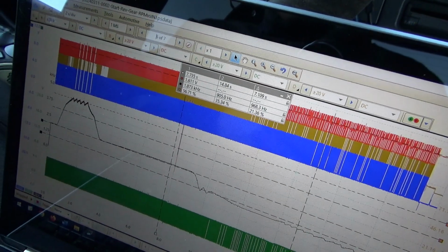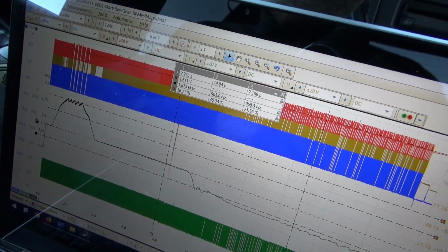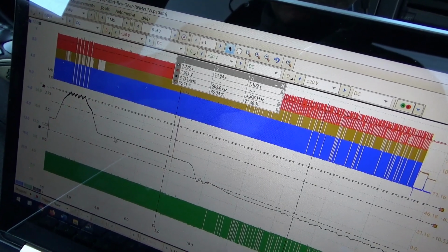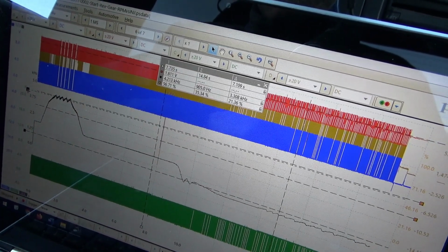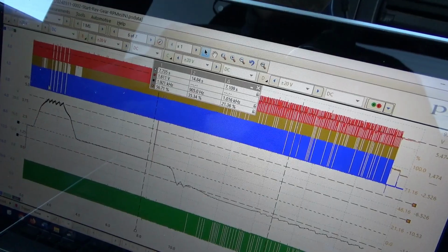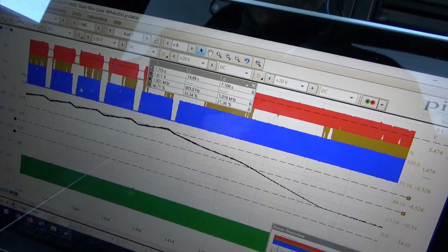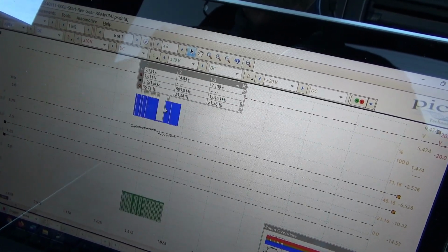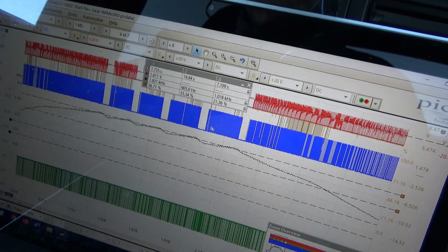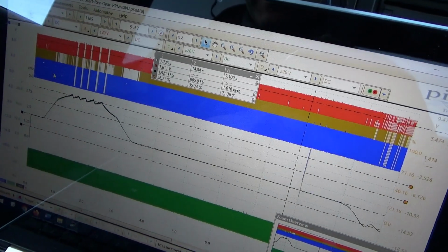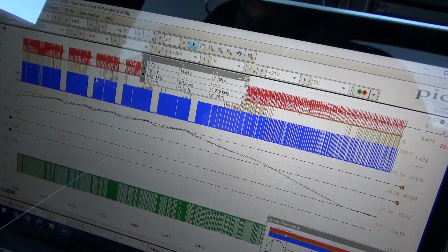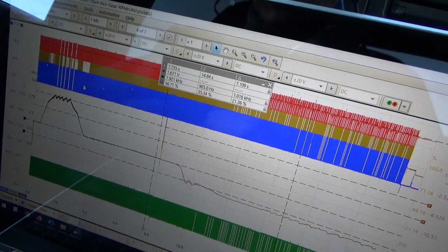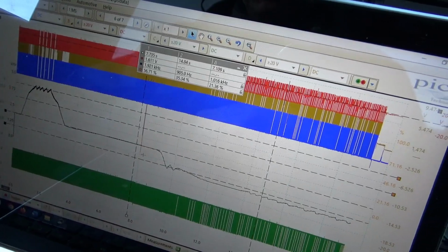And here is where it bounced off the rev limiter, and the RPMs reached 4,200 RPM. That's not good for a diesel. Again, it wasn't under load or anything. And then back down to 2,000. And you can see this fuel cut that happened. Fuel cut, fuel cut, fuel cut. That's the rev limiter, so that's working. But why is the PCM commanding such a high duty cycle when it's not supposed to?